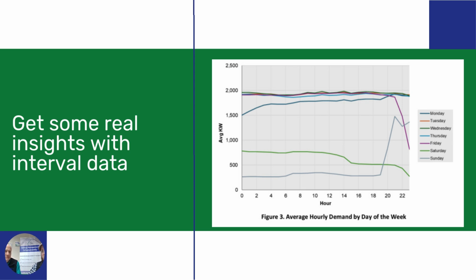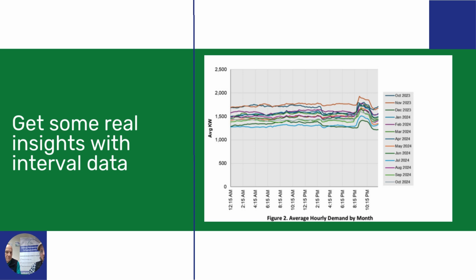But then the other thing that's really interesting is they're always running at least 250 kW down here. That's kind of startling because that's dozens and dozens of houses of energy being used day over day, hour over hour, regardless. In some cases, we've seen this happen on a building level basis or a system level basis where somebody says, hey, I'm shutting the equipment down, but we still see a base load or a continuous load here, and then we can quantify that.